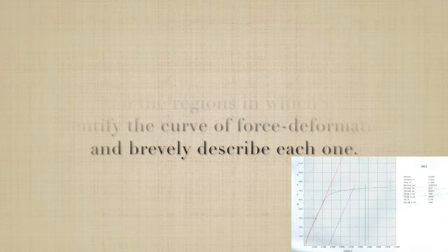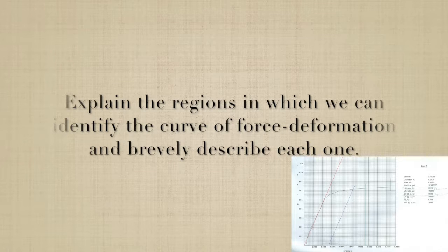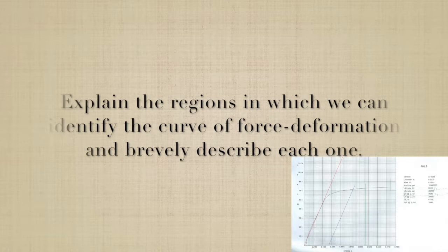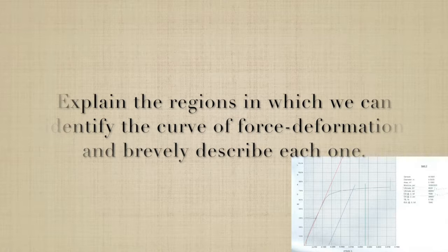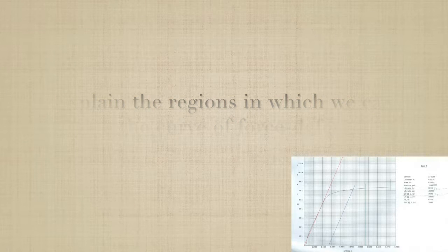In the stress-strain curve, the regions identified in the table are the modulus of elasticity, which is the blue line that shows the behavior of the material when a force is applied. This value shows the changes with stress. The limit of elasticity is a straight line that shows the 0.2% of deformation. It shows the maximum tension that a material can have without suffering permanent deformations. To the left of this line is the elastic region, and to the right the plastic. After these is the resistance to the maximum tension, which is the green line. And at the end of the graph we can find a black line, which is the breaking point.